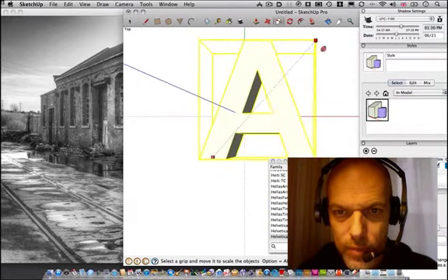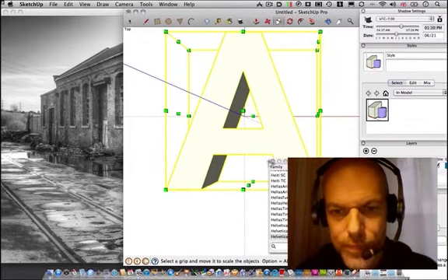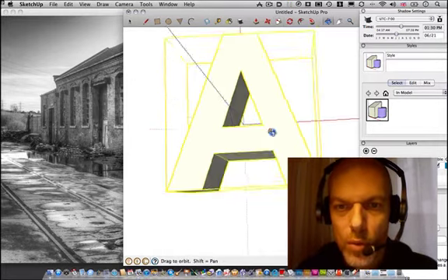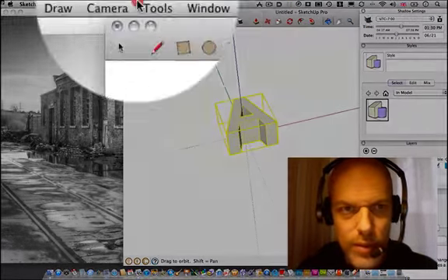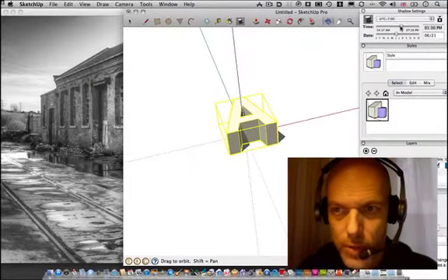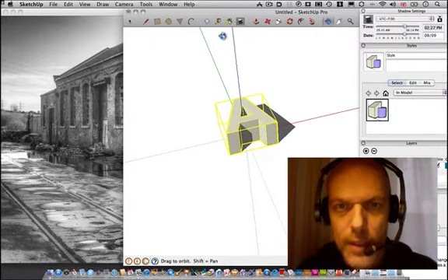That's a little, like so. Just zoom out, like so. What you can do, let's get rid of that, and if you notice when you orbit, it's sort of flat on the ground, and you can test this out by putting the shadows on. You can notice the shadows appear. What you can do is just set your shadows to the way you want it, like so, and then rotate your object.